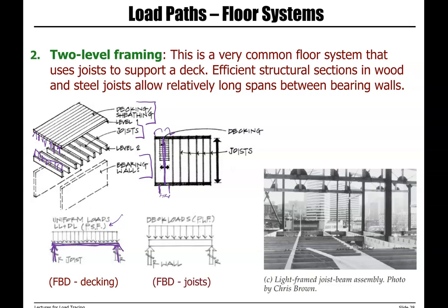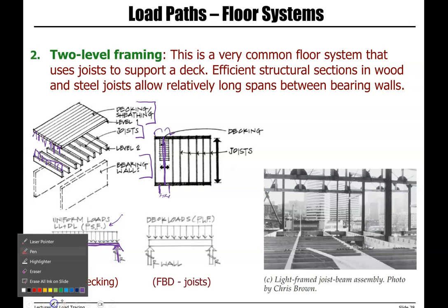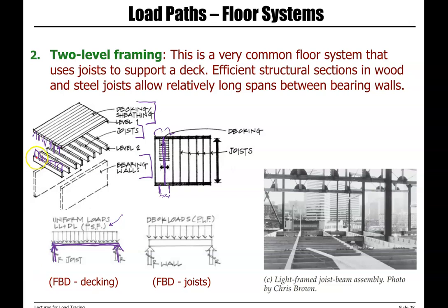Then we can draw the free body diagram for a joist. So we look at a joist and we do a free body diagram of that joist. Load is now in PLF. Then we calculate these reactions, and the reactions are the loads transferred to the bearing wall.